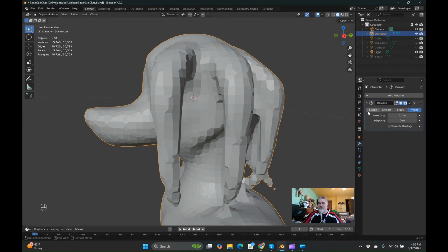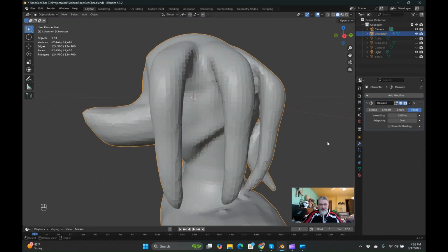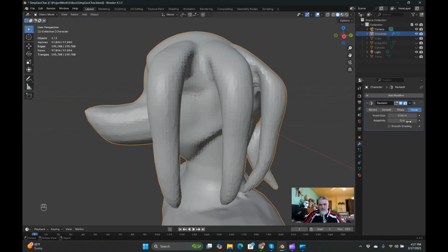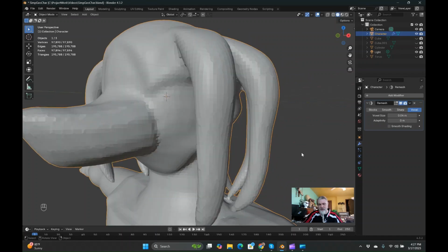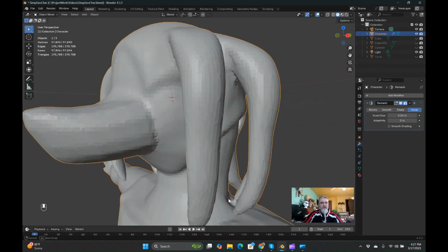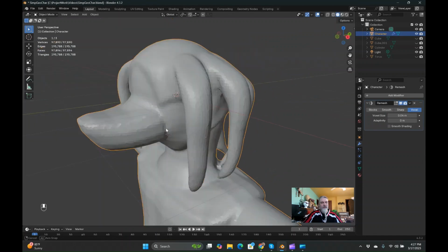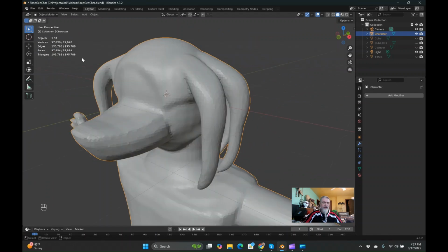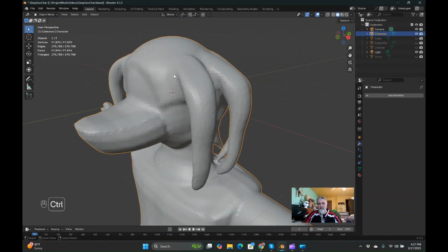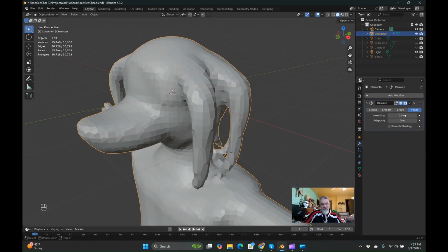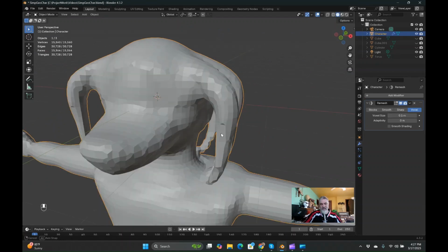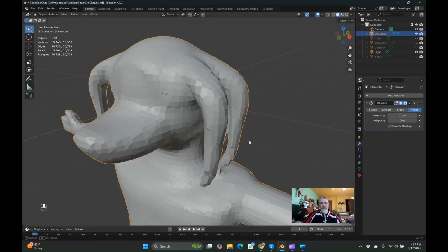I could try adjusting the voxel size, and it seems to be doing a much better job. There's still a connection here, but that's a lot easier to deal with than it happening in multiple places. Now, here's the problem, is if I look and if I apply this, this gives me 97,800, nearly 98,000 vertices. I'm not sure if I'm a fan of that, as opposed to the 15-some thousand. Now, granted, there was a lot less detail, but there's always that trade-off to be aware of.